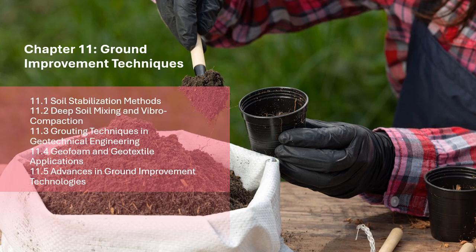11.4.1.2 Applications of geofoam. 1. Lightweight fill for soil stabilization. Geofoam is widely used as a lightweight fill material to reduce the weight and stress on underlying soft or compressible soils. Its use is particularly advantageous when traditional fill materials would result in excessive settlement or cause damage to existing structures.